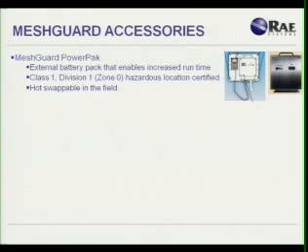And the real key feature of it is that it's hot swappable in the field. So what that means is you can have detectors, you can have your battery. This goes for 20 days on an LEL detector. When it starts to get low, it'll give you an indicator that it's low wirelessly through the detector.